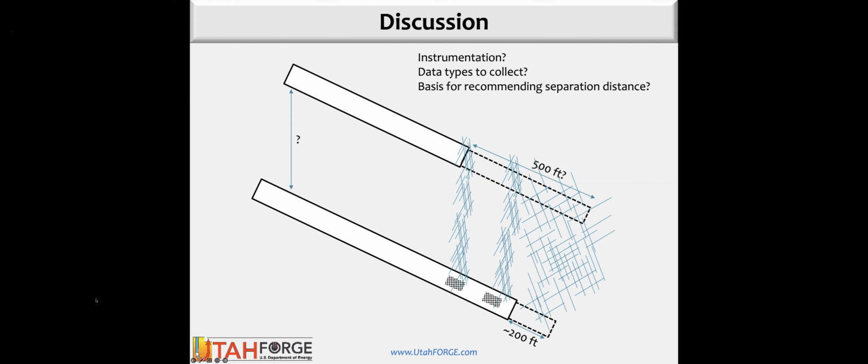The stimulation plan is actually twofold. To address some of the earlier questions, the first stimulation would be done with rig pumps or a pump truck brought on site immediately after the drilling of 16B. There would be no additional or large-scale stimulations at that point, and no plan to do additional perforations.